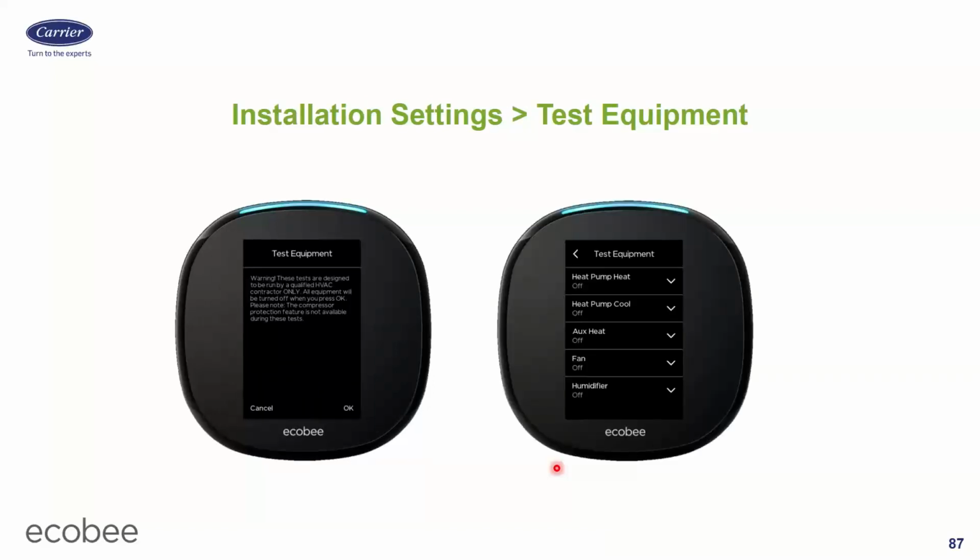After we get through the equipment and threshold screens, there is one other screen on the overall installation menu. The third one is called Test Equipment. So if you click on Test Equipment, each one of your outputs will be on here, right? So whether it's AC or furnace or heat pump or auxiliary heat, fan, humidifier, dehumidifier, anything you've wired to those 6 output terminals, seven output terminals, you have the ability to force any one of those on and make sure that they work here. This is the way you want to do it instead of going to the thermostat and just jacking the set point really high or really low.